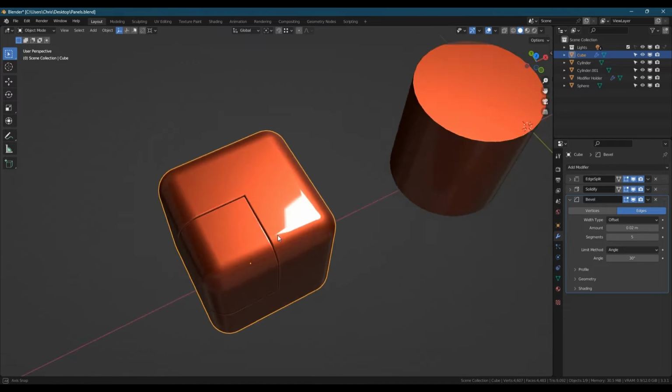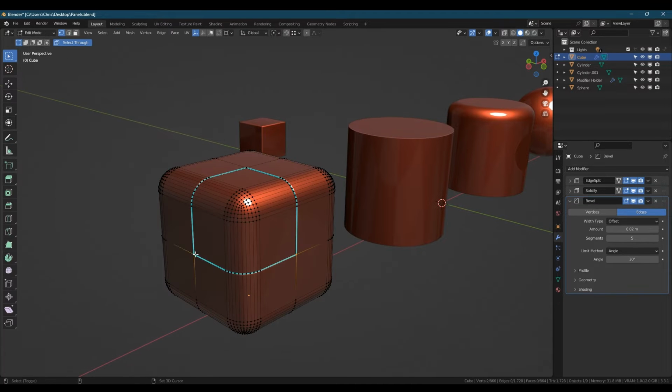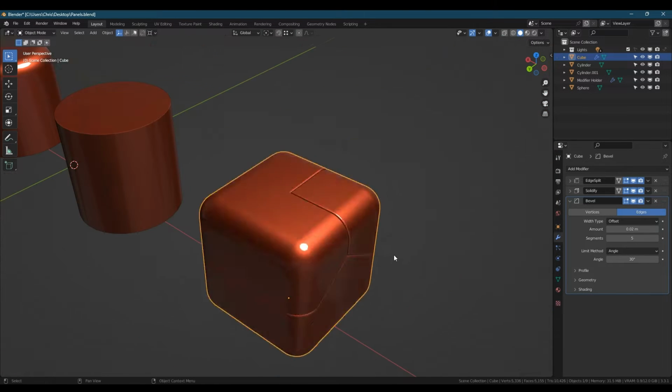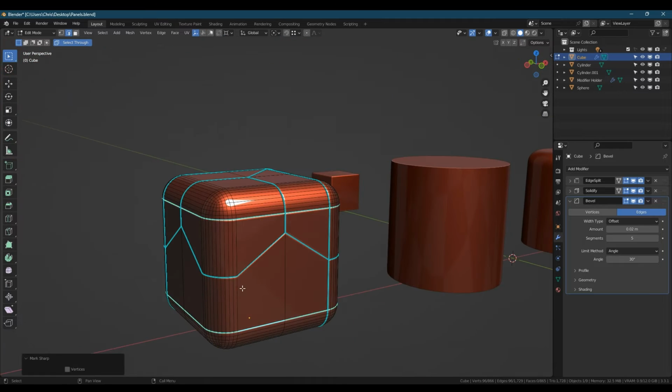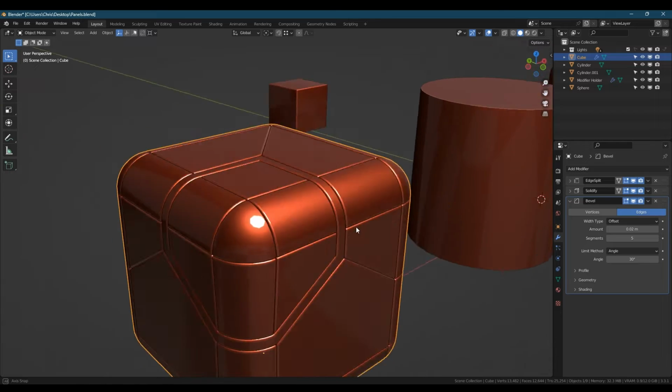We can now do pretty much anything to the lines on the surface of this cube and have them act as panel lines. It can get messy if your cuts are too close to existing geometry, as the bevel will either clamp or overlap, causing distortion, and similarly it's why we use a low amount on the solidify modifier.